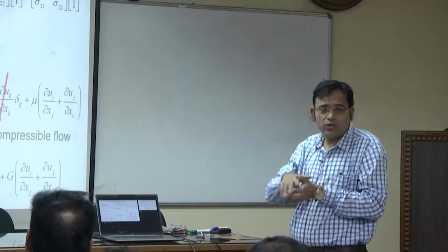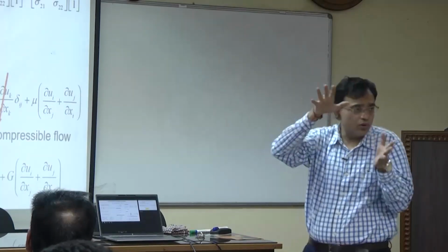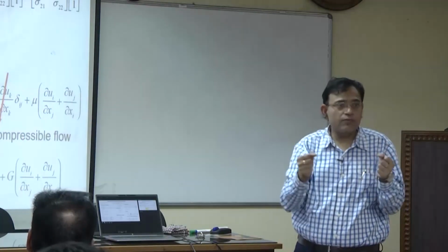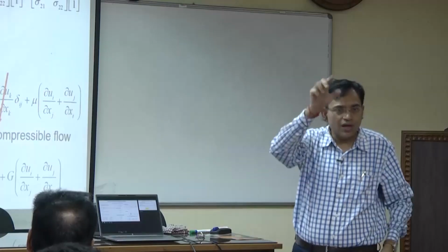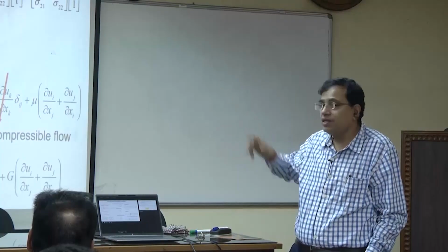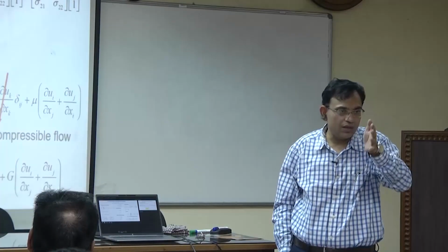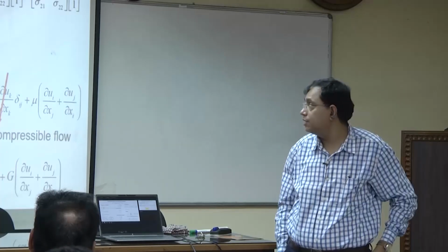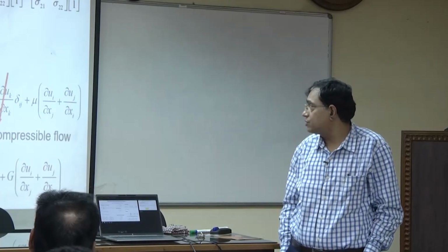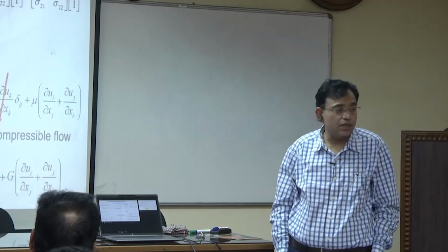When you have a fully horizontal interface before the flow, before you have a flow and you have made a channel, so you have a wall and the wall is pretty horizontal, so you have theta equal to 90 degree, that means if you draw a normal to the wall its angle with the horizontal is 90 degree. So, you have n1 as 0 and n2 as 1, because n1 is cos theta, n2 is sin theta, the 2 direction cosines.